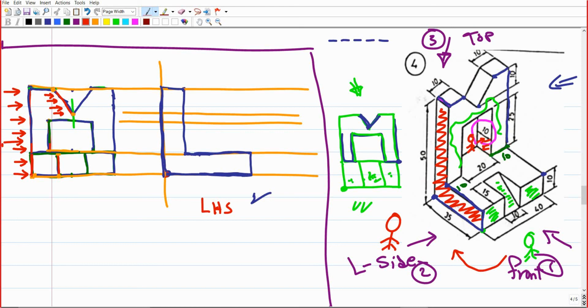You're going to see this face, right? Okay, this face will be seen like a rectangular shape. So you have to represent this rectangular shape in its area, which should belong to this line. Do you see this line? Like you already assume that you're standing inside the opening and you're going to look at it from this side. So this edge should be seen. So if you project just this edge, it will be projected into one line here and there is another line here. But this line should be seen like a dash line.